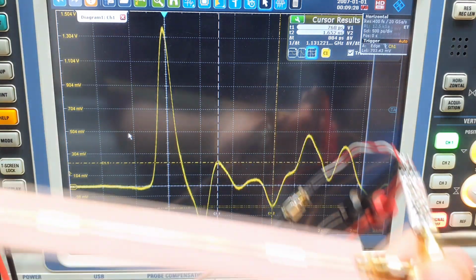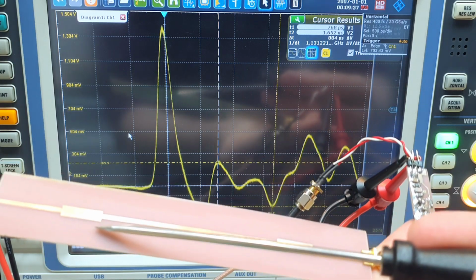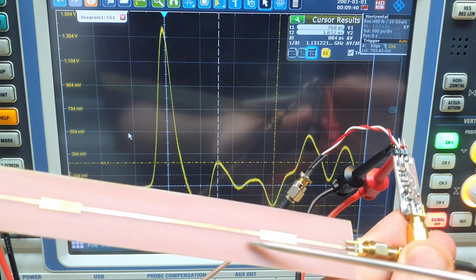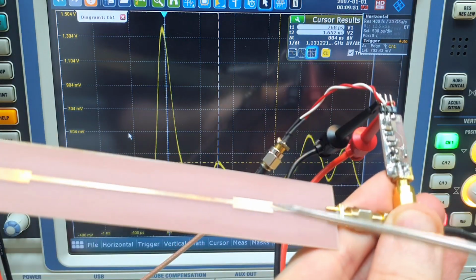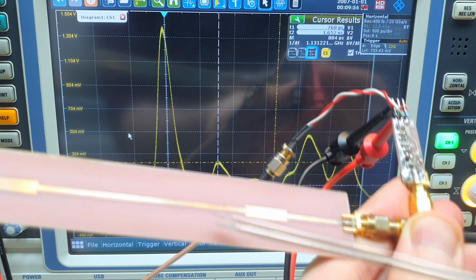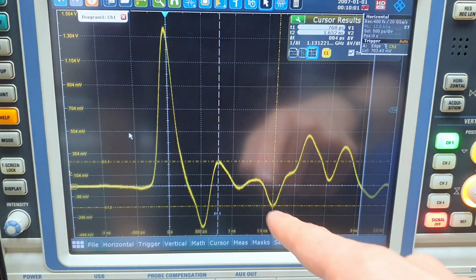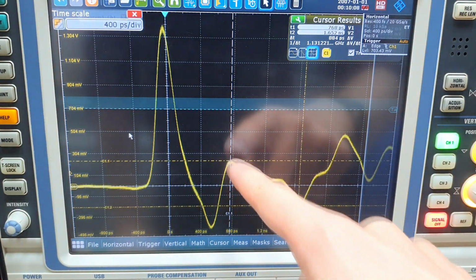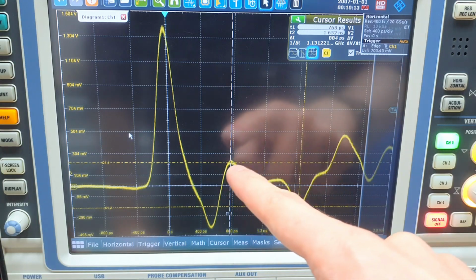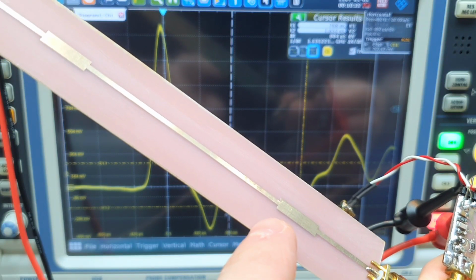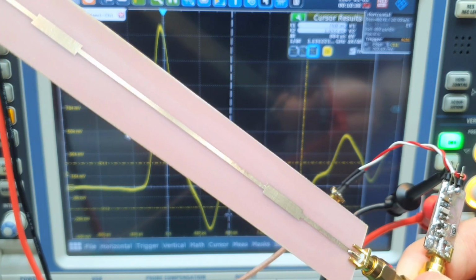And we are interested in measuring the difference between this discontinuity and this one here, because this length in between, or reference length, is the well-known physical length. So we need to measure a low to high transition and a high to low transition. And this is exactly the 2 points that are marked here, right? We have this moment here and this moment here. And the difference in time between these 2 peaks is double the time the wavefront took to propagate from this point to this point. And why it's double? Because we are measuring reflections.